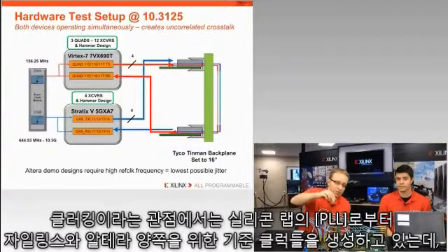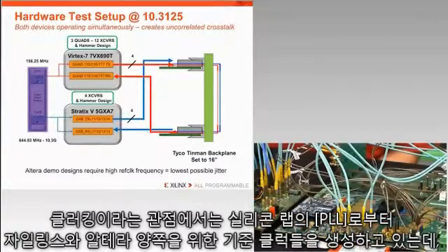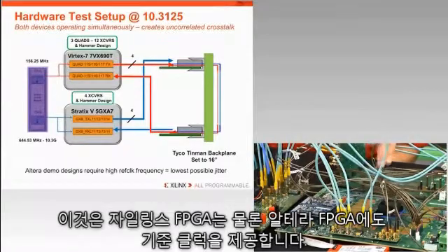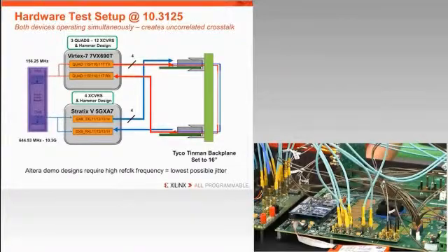From a clocking perspective, we're generating reference clocks for both Xilinx and Altera from the Silicon Labs PLL that's on the superclock module on the Xilinx board. It provides a reference clock into the Xilinx FPGA and also into the Altera FPGA.